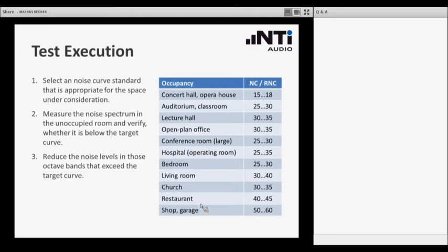For instance, in the high frequency range or in the low frequency range, and this information allows you to optimize the acoustical situation in the room with a very targeted measure, to apply damping material which is able to lower the background noise level in the corresponding frequency band.